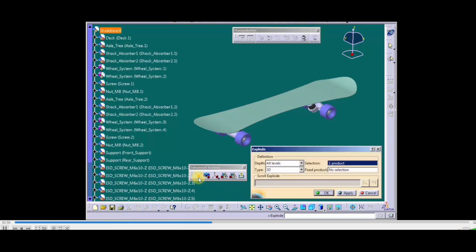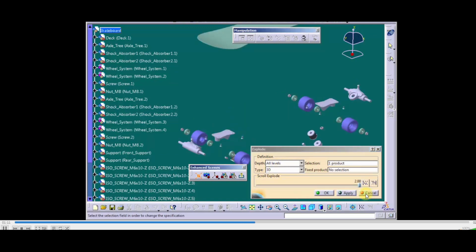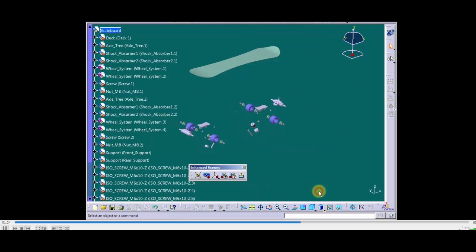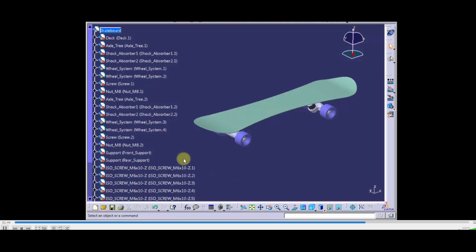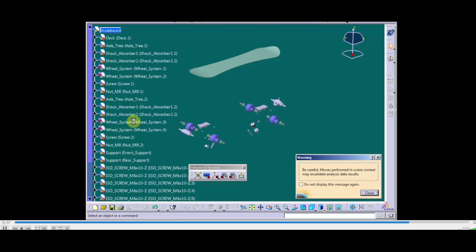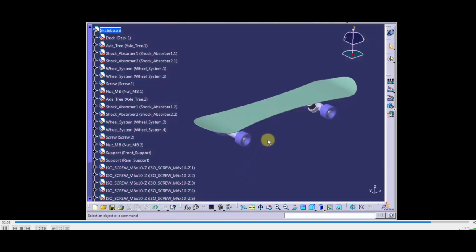So in enhanced you can go with the exploded view, which is in the background. You can save this one and go for that. When we go for this enhanced, double click on it and it will show you that exploded view. There are different types of enhanced properties also. You can create multiple enhanced views to see the points of each and every operation of your component.